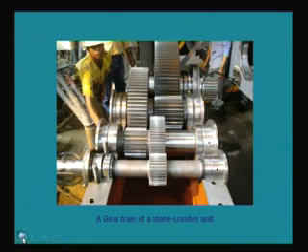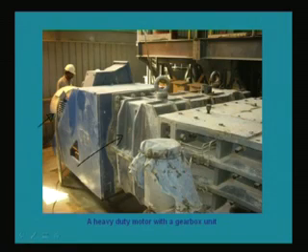If we put an accelerometer maybe here or here to measure the vibrations, we can know when this particular fault is appearing in the machine. Just by observing the vibration from outside, we can know the condition of the machine inside.